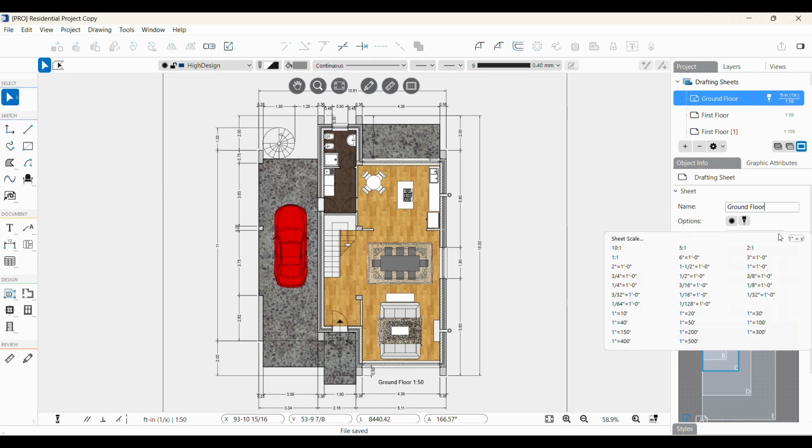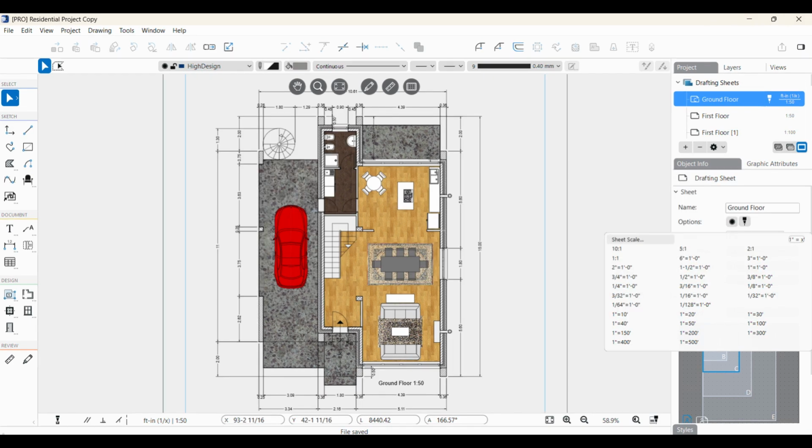Drawing scale. To change a drawing scale, enter the scale ratio, e.g. 1 to 200, or click the pop-up arrow to open the menu of predefined scale. When using imperial units, it is possible to switch the scale representation between ratio and verbal, e.g. 1 inch equals 1 foot, by clicking the icon on the drawing scale pop-up menu. It is also possible to enter a scale value below 1.0, such as 2:1.